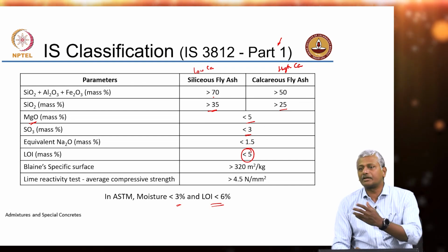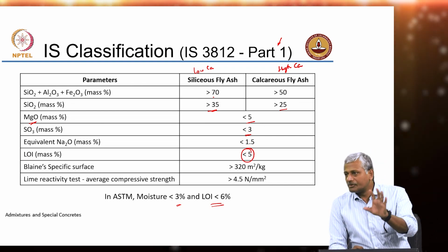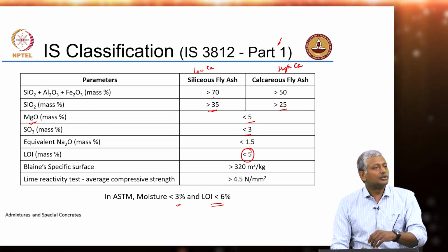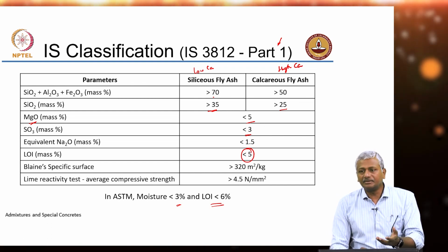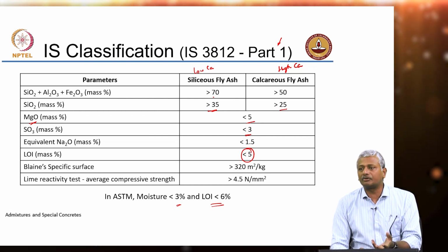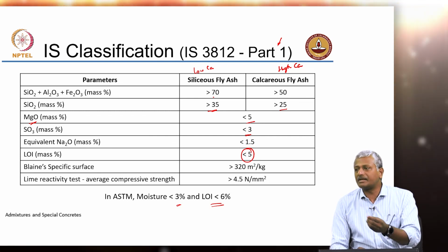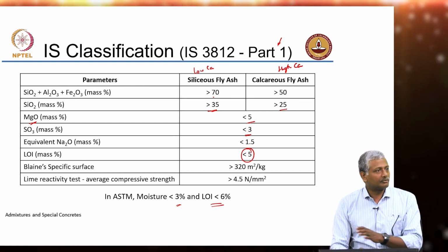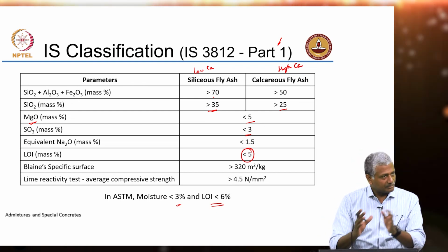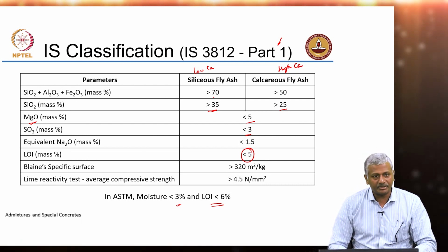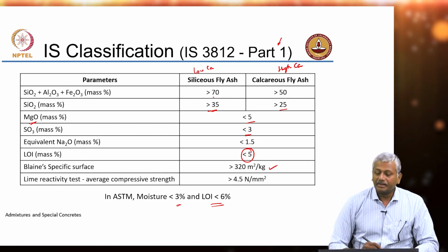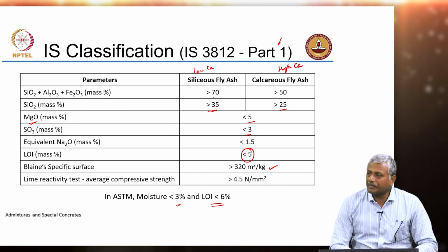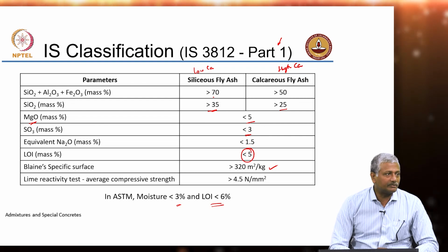Usually when you do processing of the fly ash, instead of just directly collecting and using it, if you collect it, process it and use it, you would choose to make it finer, because then you can control the rate of reaction. You can increase the reactivity by choosing a finer fly ash rather than using the full particle size range of fly ash. You are making sure that you are only using finer fly ash. In such instances, use of particle sizes that could lead to such finenesses can be helpful if you want a higher reactivity.